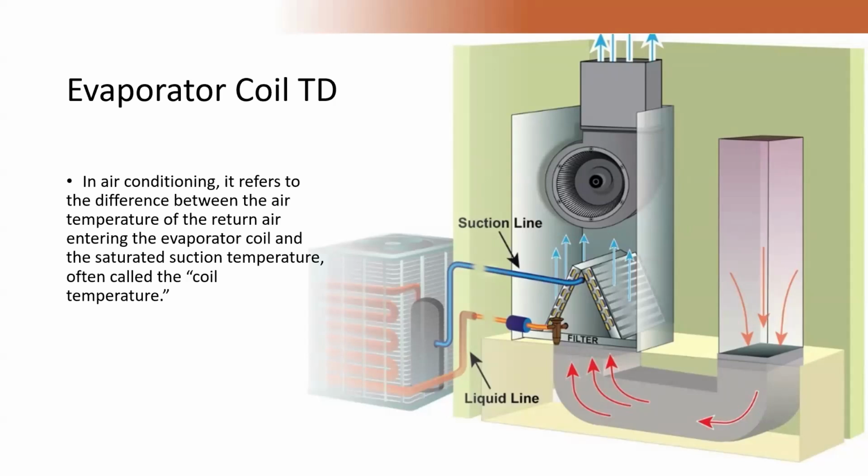Long line sets, compressor's working a little harder. Vertical changes, that compressor's working a little harder. Clogged filter dryers, it might not be causing the pressure to go down, but it could be affecting our refrigerant flow. It's going to cause that compressor to work a little harder. All of these things are how this system is moving that mass flow rate, refrigerant flow rate.